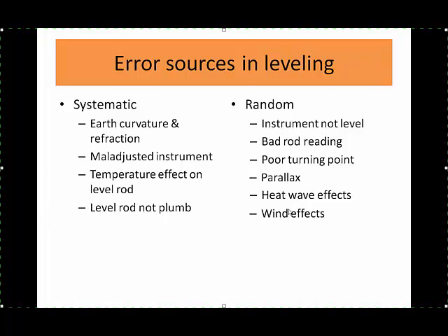Likewise, the wind can affect the rod by blowing it out of plumb. If you take a telescoping rod and run it up to 25 feet, it's going to be hard to keep that thing still. Likewise, the wind can affect the legs of your tripod and make them vibrate, making it difficult to read the instrument while it vibrates.